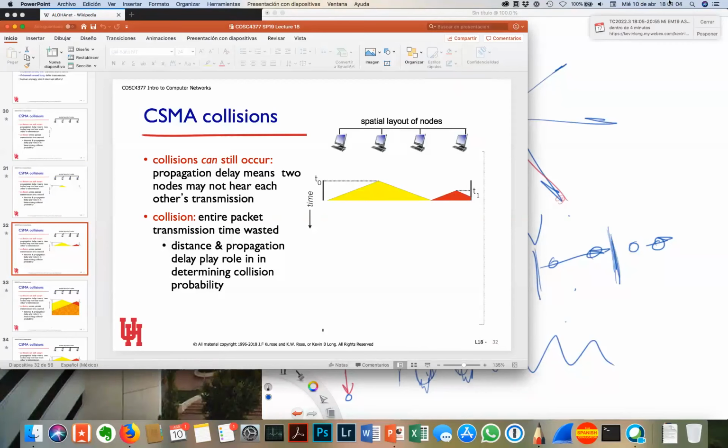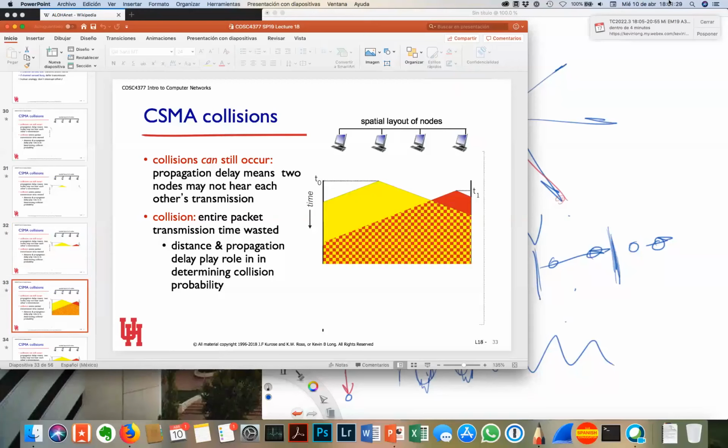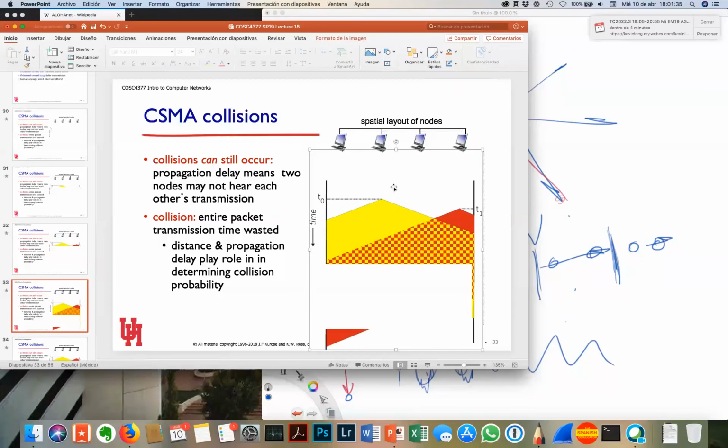But what you hope is that you've designed your transmission protocol and defined exactly how ones and zeros are defined and in what combinations and patterns they can appear, that this change that results from these 2 signals combining will result in something that you will immediately recognize as invalid. That's the prayer. So this begins to propagate its way back across the network at the same speed it came, and it's not until you get down to this time here.